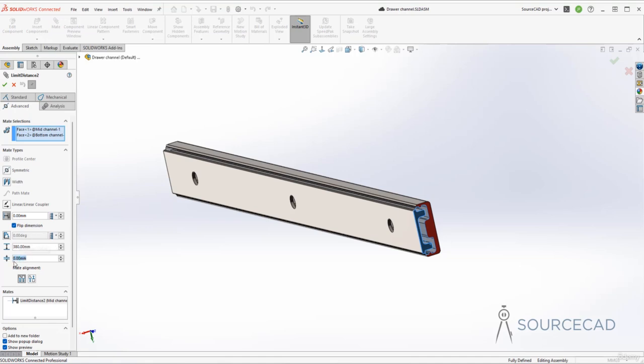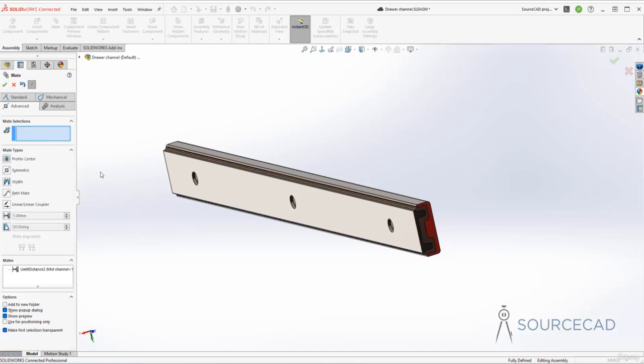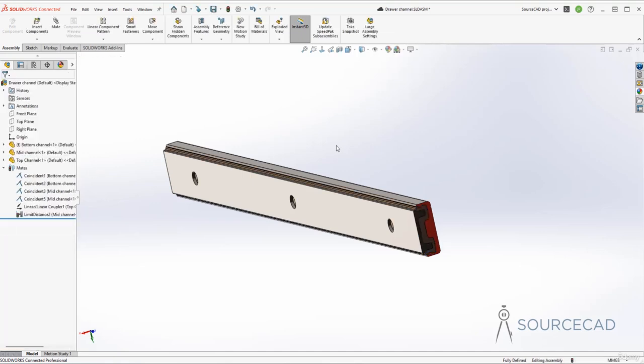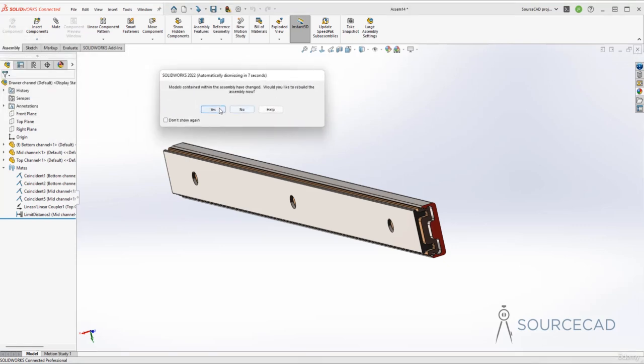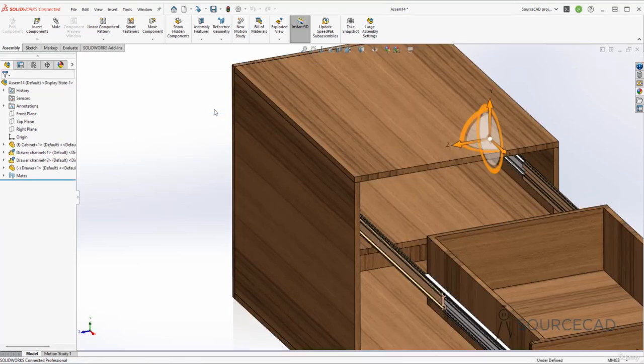Let's just change this minimum value to 5. Now we wanted 5 unit outside. All right. So with that 5 unit gap, now this should work. So let's just click OK, and let's just save this one now. So save this and close this. Now this will give you a prompt like this. Do you want to update the assembly? Well, yes. And the assembly is also updated here.